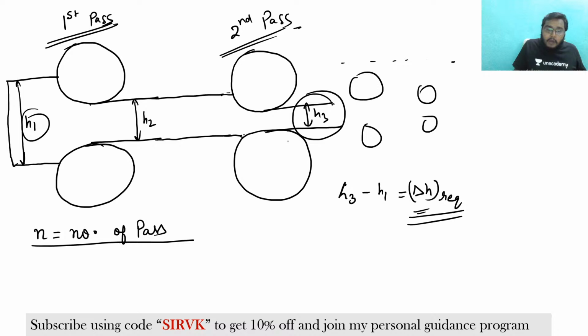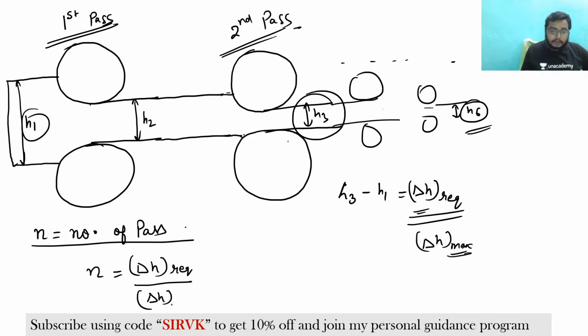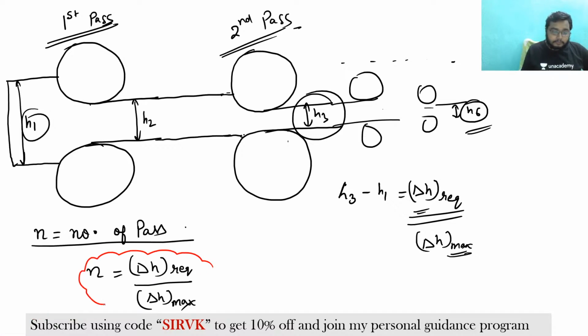Now this delta h can again undergo different processes, and it can also form something like delta h6, which is the maximum draft. So there is another quantity, delta h maximum. If I want to find the number of passes, n, it is given by delta h required divided by delta h maximum. Right or wrong? So this is the concept of pass.